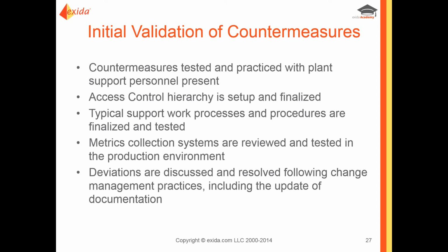Any deviations you discover need to be resolved, and they all need to follow your change management practices. All of our companies today should have management of change policies and practices. You may need to tweak those to make sure that cybersecurity is managed in the process plant world with a similar level of rigor as your safety instrumented systems.